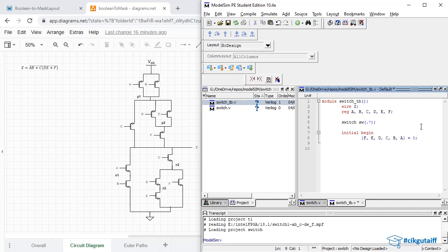All right, so next I'll have my repeat block. Well, 6 bits is rather large if you want to simulate every single possibility, so I'm not going to do that. I'm just going to show about 40 patterns. And then after the initial application of all 0 at the input, after 5 simulation periods, I'm then going to increment this bus, if you like, by 1.